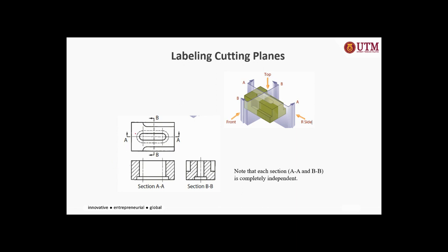And as you can see from this view from the top, when we cut the equipment at AA, this is what we see. This part we will throw away, and when we look at it from this direction, we can see the knife pass through here, and here is empty, so there's nothing. And then this part again, the knife passed through. So you see the detail as such. And for cutting on section B and BB, you will see that the result of the drawing is such.